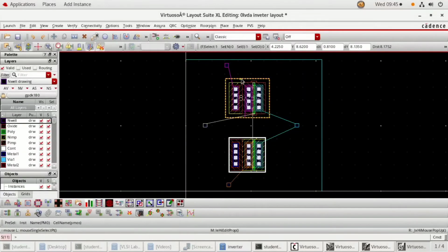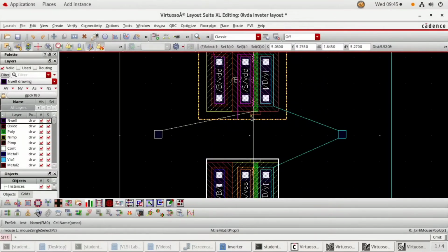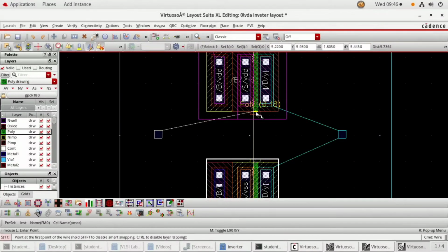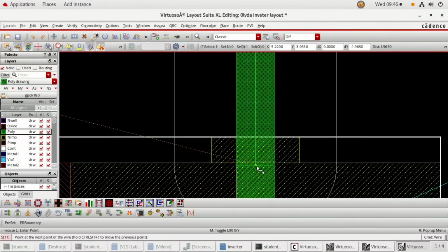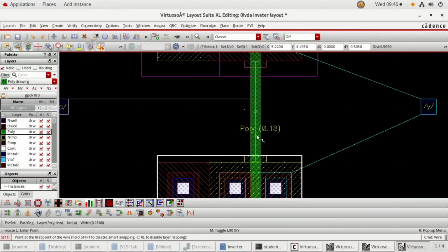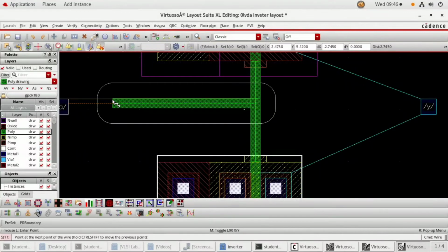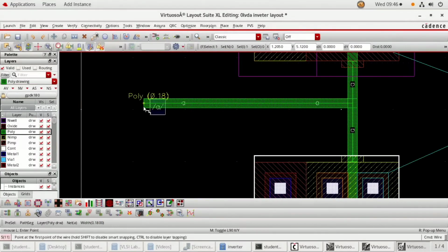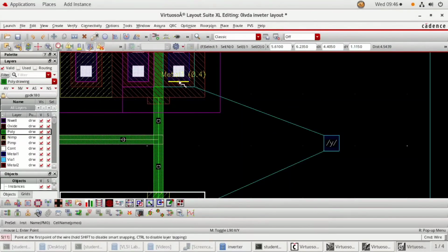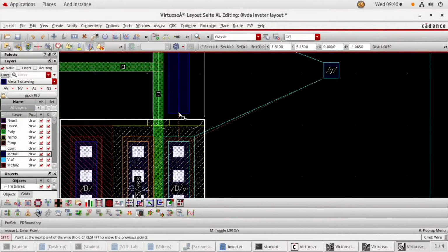Depending on the design, I can select the body type to be attached or it can be integrated. Now press P on the keyboard so that you can see the cursor has changed. It's indicating that you can make the connection or extend it. So carefully connect all the layers with each other according to the rat lines that have been indicated.